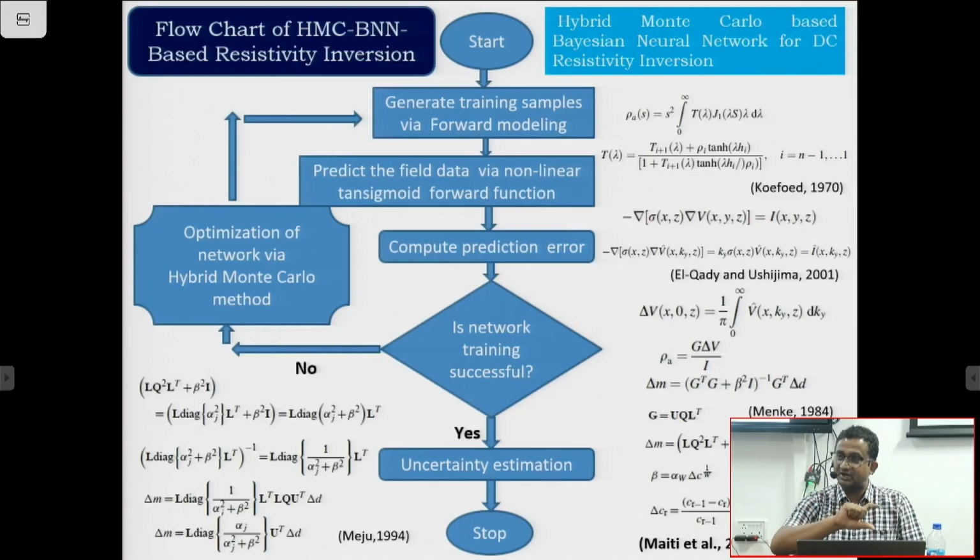From the survey, we get the apparent resistivity, the resistivity of the combination of the whole layers, since there are two or more layers in between. So what you get from the survey is the apparent resistivity, and then you convert it to the true resistivity through the conversion process. So which is the thickness? Thickness is the thickness from the surface to the layer. But there is no thickness in that equation, in the inversion equation.